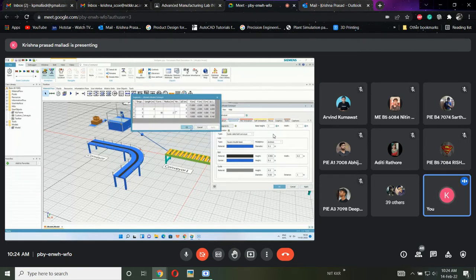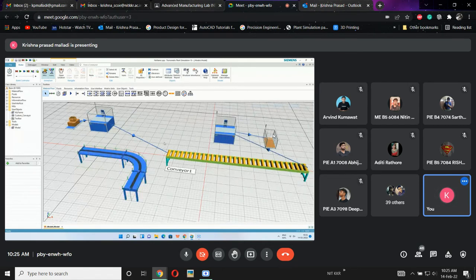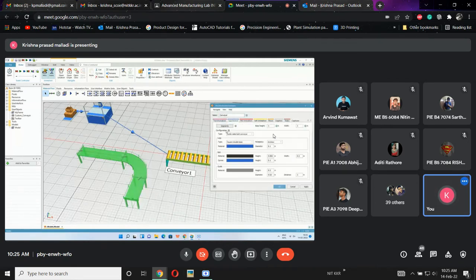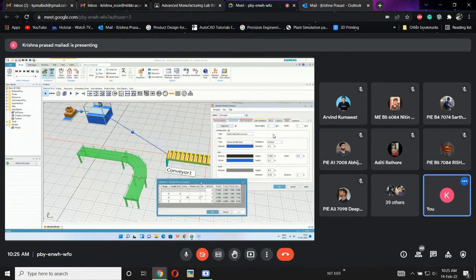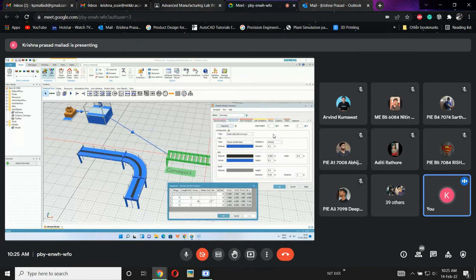Okay. See, I'll show you. Whenever I click this modification, press this one and select M. How many nodes are there here? 1, 2, 3, 4 nodes. That representation was this one. Starting point 2, 3, 4. Those are 4. Length 4. This is having 4 in length. The second one is curvature. This has a curvature of 90 degrees, the radius is 2 and this length is 2.